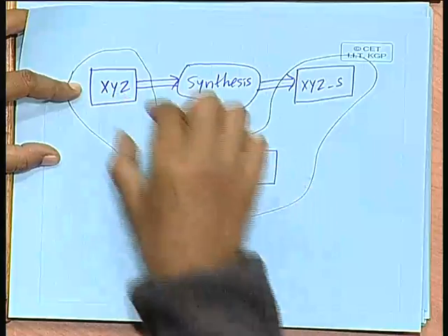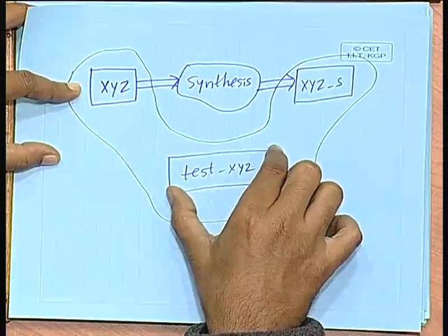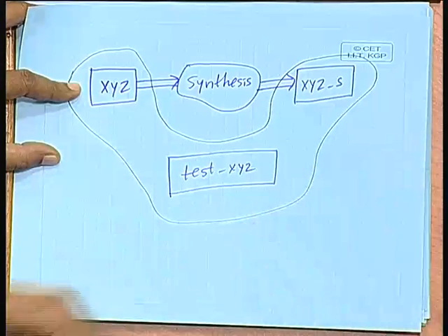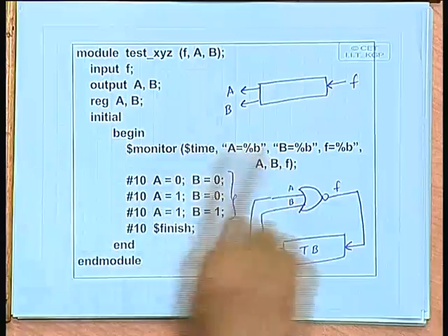What I am saying is that whenever you are doing this kind of instantiation, these are defined as individual Verilog modules, and whenever you define a Verilog module, just like a function you write in C, you have to specify all the signals coming in and coming out. That has to be there as part of the parameters. This is mandatory. But the top level module, in contrast, does not take anything in or anything out. That does not need any parameters.